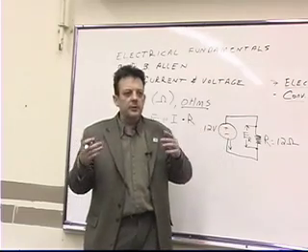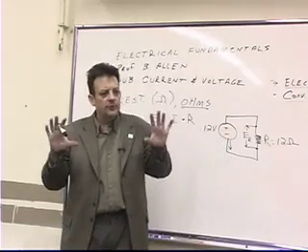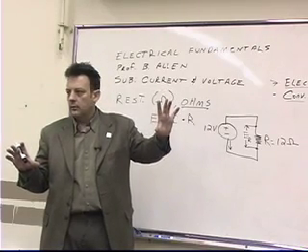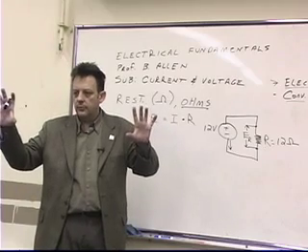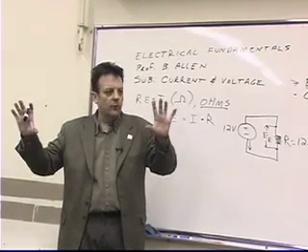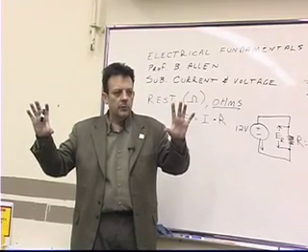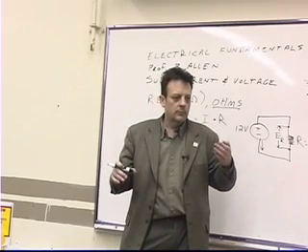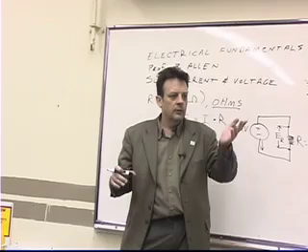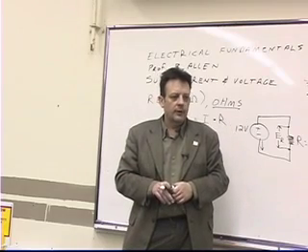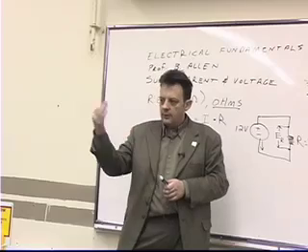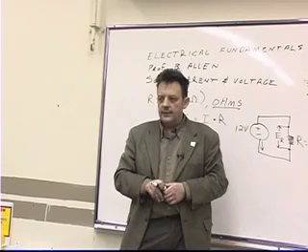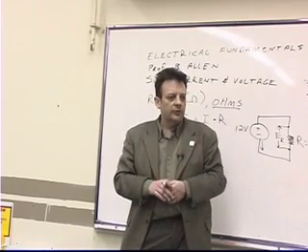But for most people, it's kind of common sense that if you only have two things in a circuit, an active source, like a lead-acid battery, and a hairdryer or a resistor of some kind, they're both going to have the same voltage on them, right? In other words, what is the voltage coming out of the receptacle in your bathroom? 110, 120. Federal law requires the voltage that comes into homes to be approximately 118, plus or minus 8%.